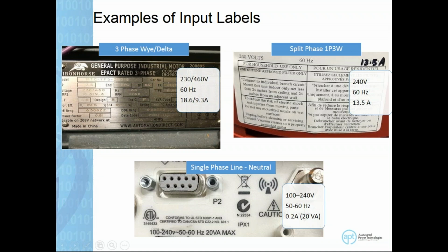One thing I will tell you is that in a household setting, the limitation of power comes from the power breaker. The breaker is a 15 amp breaker, and some of the national fire code would not allow you to run more than 80% of the capacity, so 80% of 15 amps. So the max current you could get out of a household setting could be around 12 amps.